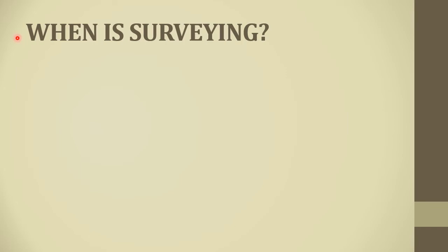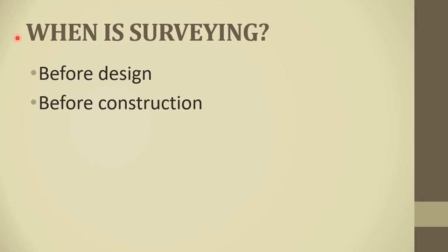So when do we have to do surveying? Well, we have to do it before design. As we remember from part 1, we need to know what the layout of the land is, how it rises and falls. Do I have to level it? I need to know it before construction because I have to know what those points are and where I'm going to have to be cutting and what I'm going to measure from.